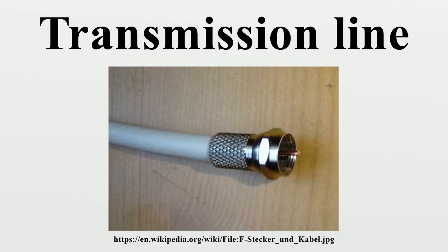Transmission lines use specialized construction and impedance matching to carry electromagnetic signals with minimal reflections and power losses. The distinguishing feature of most transmission lines is that they have uniform cross-sectional dimensions along their length, giving them a uniform impedance, called the characteristic impedance, to prevent reflections. Types of transmission line include parallel line, coaxial cable, stripline, and microstrip.